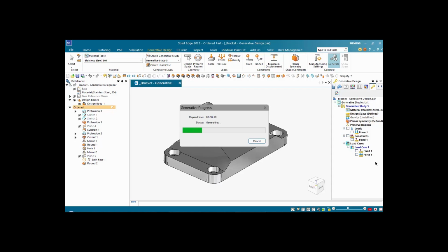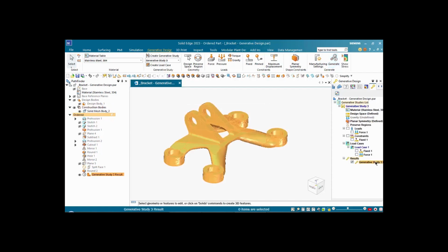One thing you need to be aware of is that we're talking here about hybrid modeling, which means we combine mesh bodies with B-rep type of geometry, which is usually developed when you use your CAD modeler. It gives us really great flexibility because afterwards we can clean up the model, we can adjust geometry as we go, and that allows us to actually work with the final result, with that organically shaped body.